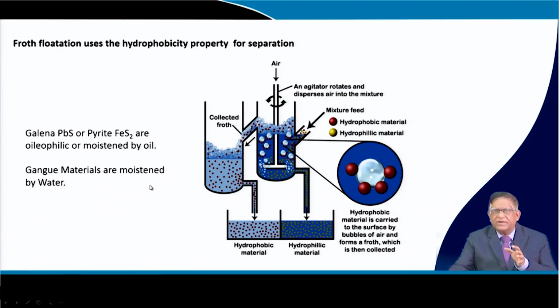This thing is considered, and that is how they put things in one chamber. When the whole mixture of the feed comes in, both hydrophobic and hydrophilic materials are entering. Then when the bubble is being formed, the hydrophobic material, that is your oily substances, will get attracted to the bubble, and they will come as a froth at the top, and they will be taken out. So, like that you have to have it.